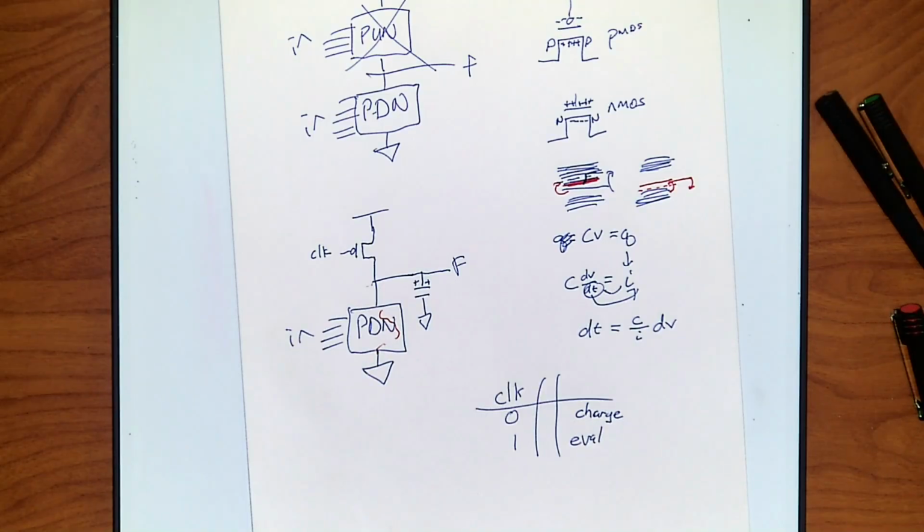Now this fits all within one cycle. That's exactly what you need for a computer. This is sometimes called pre-charge evaluate because I pre-charge it before I evaluate it, a charge and a discharge. It's also called dynamic logic. Since I only have one PMOS in this whole thing, and it fits exactly in, that's awesome, right? We have the really fast pull-down network. We only have one slow gate, but I've hidden it completely by my clocking.